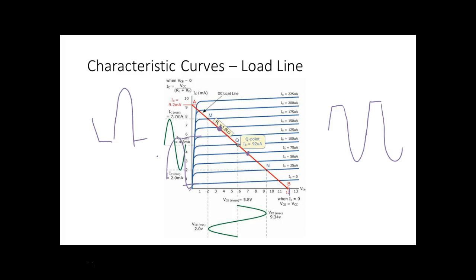So that means eventually, if it's designed right and you put enough signal in, you're going to get distortion out of just about all amplifiers. So usually they limit the actual volume control below where the circuit's saturated or cut off. You could add resistors, but every time you put a resistor in series, you're adding cost. I could use rheostats, and I could set the suckers directly in the center. But I'm going to sell 1,000 of these things, and you want me to add 30, 40 more cents to every unit. Well, that's a lot of money that either I'm going to lose or my competitors are going to make off.